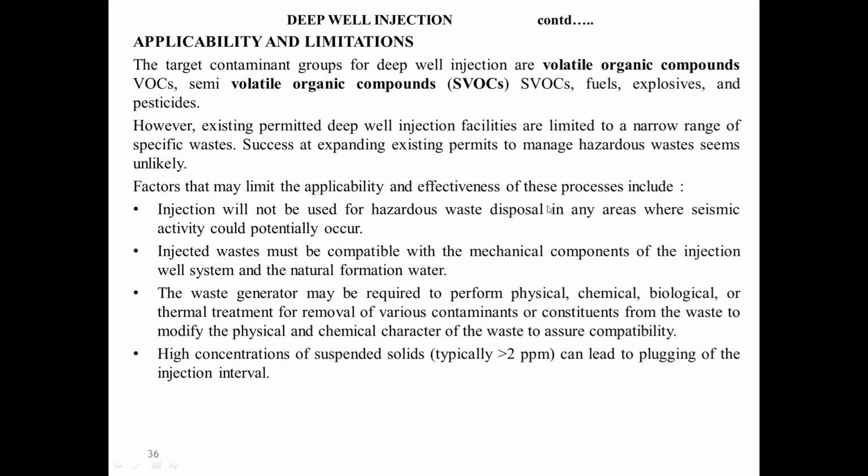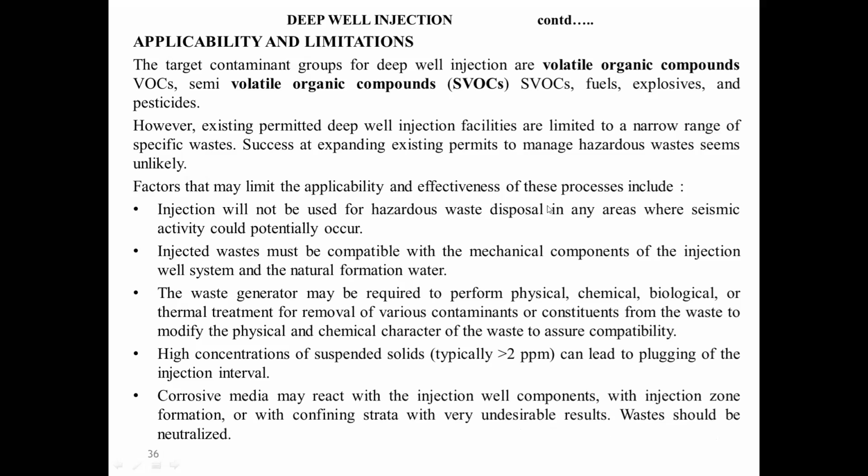Then, if it has a high concentration of suspended solids, more than 2 ppm, that is parts per million, it can lead to plugging of your injection interval, because injecting solid waste takes more time. So we are going to avoid those, or take care of these things.